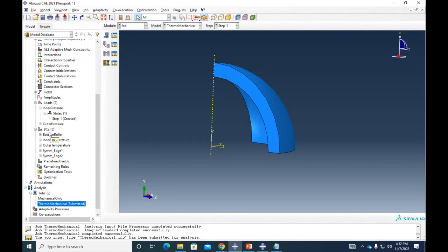What I'm doing right here is a parametric study on the load. I just varied the load from 10 to 50. So if I go to 50 megapascals and then I see that all my structure is yielding, then I decrease the load a little bit until I find more or less a ballpark in which the structure starts to yield. All right. So completed.